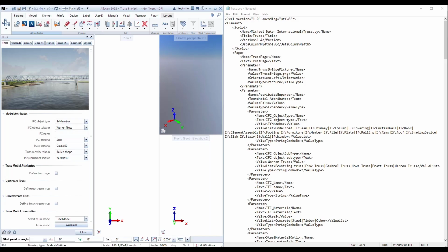The module interface is completely defined in the PYP file, which can be parsed by the Allplan software. Basically, the PYP file is an XML file, which is pretty human readable. For example, the script node here defines the overall layout and the metadata.